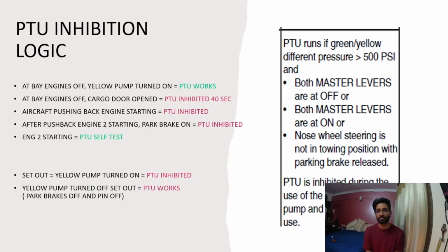At this time, once your second engine is starting, you will notice the PTU working. This is a self-test that the PTU does to ensure that the PTU works. Because in a moment the EDP2 will kick in and the pressure difference will be gone. If pressure difference is gone, this condition is not met. Anyway, none of the other things, it doesn't matter. It's AND, right? So in that case though, this won't make any sense anymore.